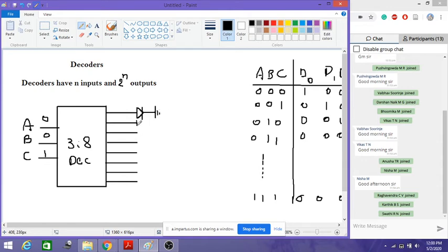So likewise there is another LED connected here. So likewise there are 8 LEDs connected and then to the ground. Assume like this, all the outputs are connected to LEDs. So now these are connected in a common cathode configuration. Common cathode means all the cathodes of these LEDs are connected to ground. So it means these LEDs will be turned on only if we give logic 1 or the positive voltage.